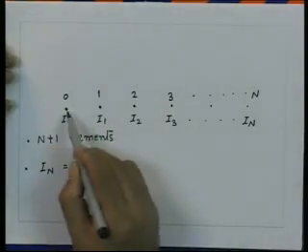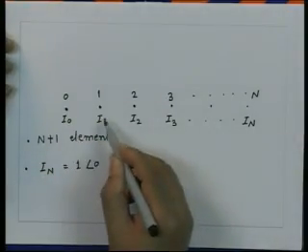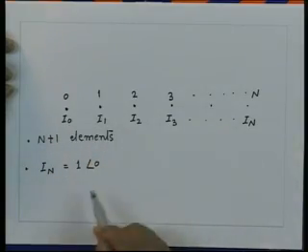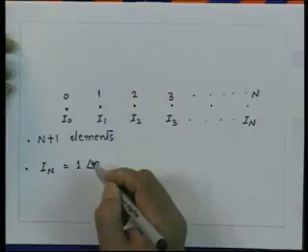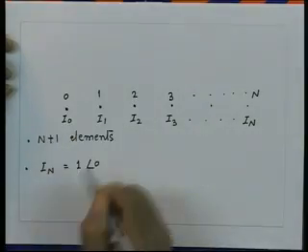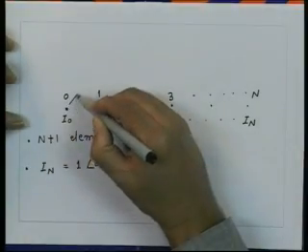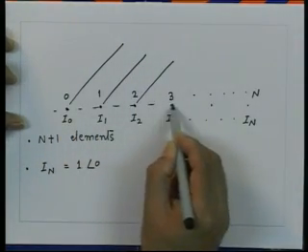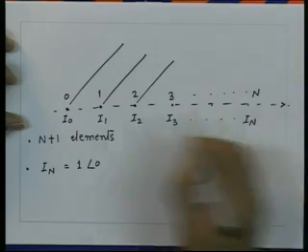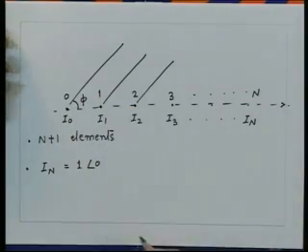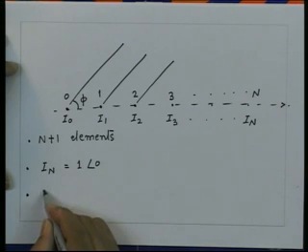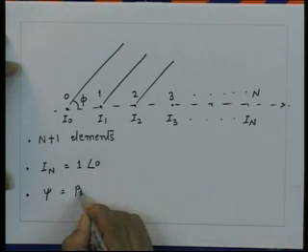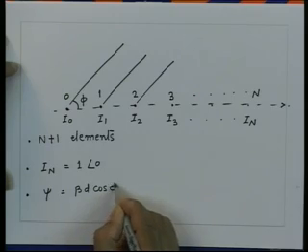Then, since the inter element spacing is constant and since these currents are now complex, the progressive phase shift which we used to talk in terms of uniform array can now be absorbed into the phase of these currents. So, we can now define the phase of the array, which is psi, which is simply beta d into cosine of phi. Again we take a direction which is the angle measured with the axis of the array, this angle is phi, and we define this quantity, the phase psi, that is equal to beta d into cosine of phi.